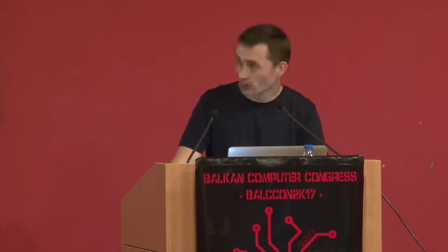So my first attempt was flying the thing fully manual. That led to what you saw. Luckily, it went on to see another day, and I was able to correct it. It was just a few settings in the flight control software, a toggle switch, to make it level itself and stay in the air.